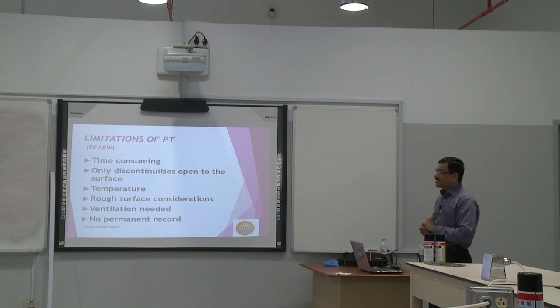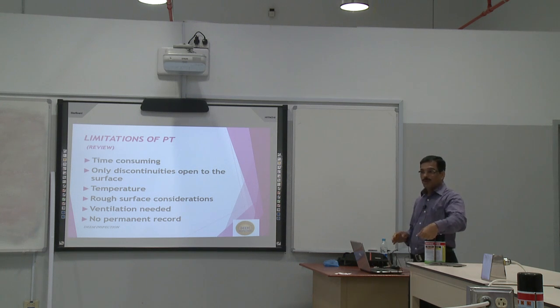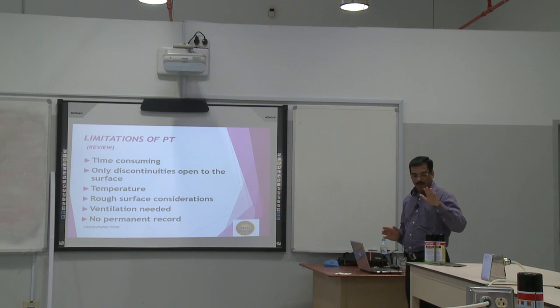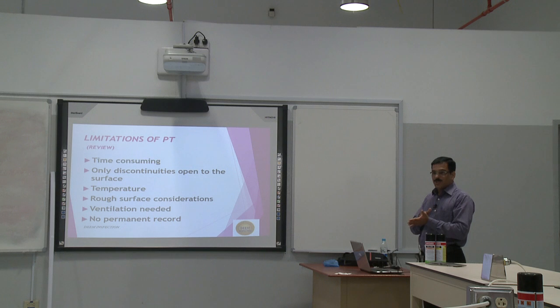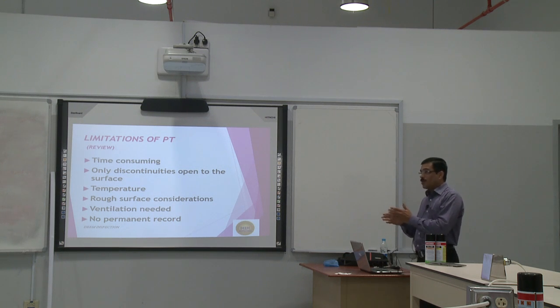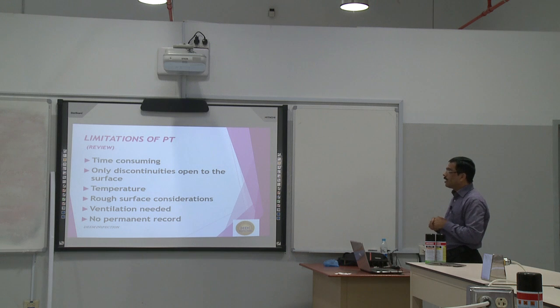What is the limitation is, first, it is time consuming. Because in magnetic particle testing, there is no time consumption. If you put a yoke, immediately we will get the result. There is no need of any waiting. But in this one, we have to wait for dwell time. Minimum 10 minutes. Or before that, cleaning process 5 minutes, penetrant application 10 minutes, developer 7 minutes. So almost half an hour we have to wait to get one indication. So that is one of the major limitations, that it is time consuming.